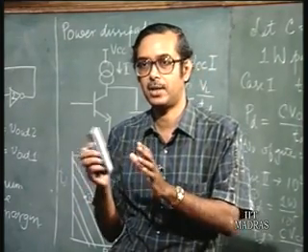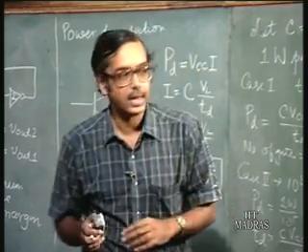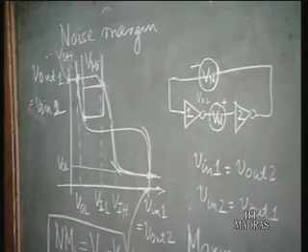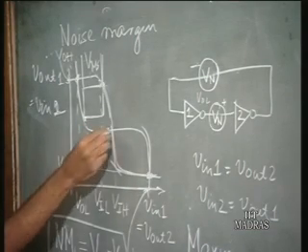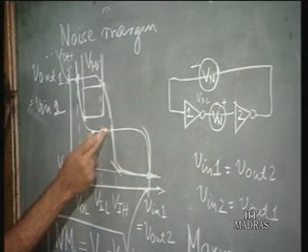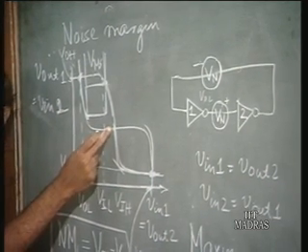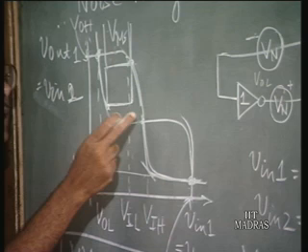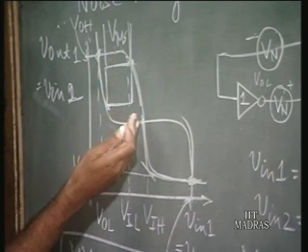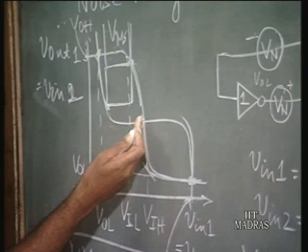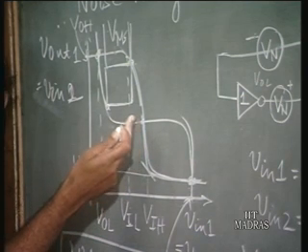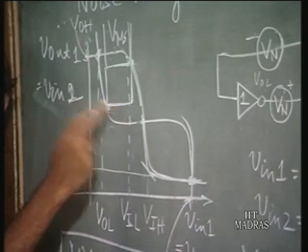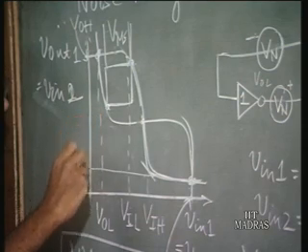So, if you have symmetric input output characteristics, that is the transition point. I will just go back to that again, this one here. Another definition I should mention: this point has a lot of significance. It is called the logic threshold. Logic threshold means that at this point, the input voltage is equal to the output voltage.